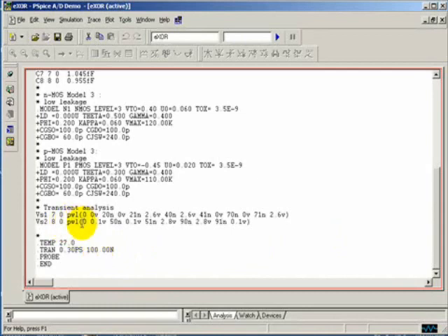The second switch is 0 seconds, 0.1 volt. The 0.1 remains all the way to 50 nanoseconds. After one more nanosecond, we raise that from 0.1 to 2.8 volts. That remains all the way to 90 nanoseconds. After one more nanosecond, we drop that to the low of 0.1 volt.